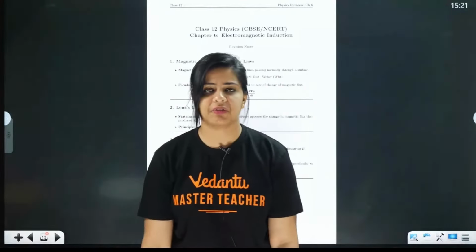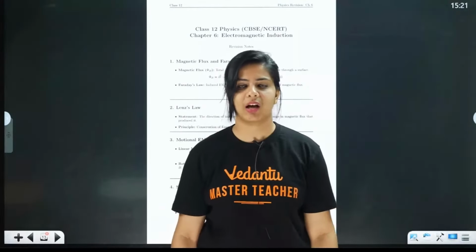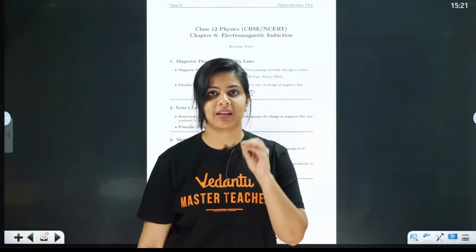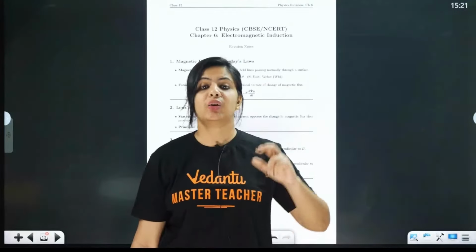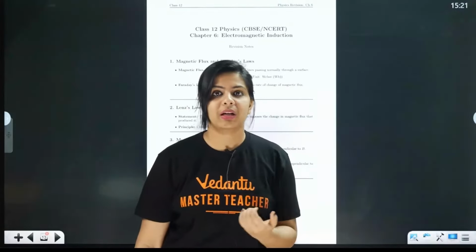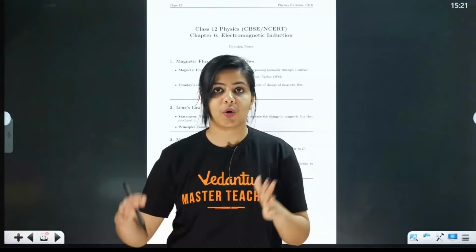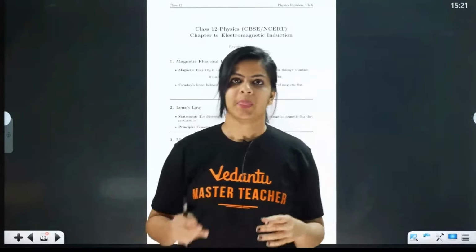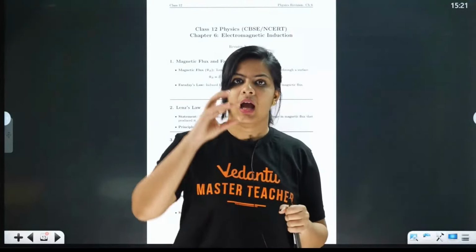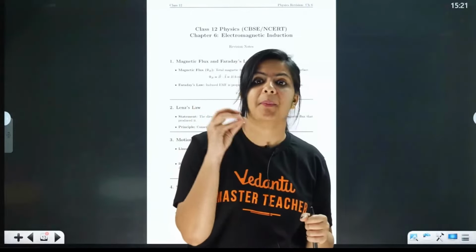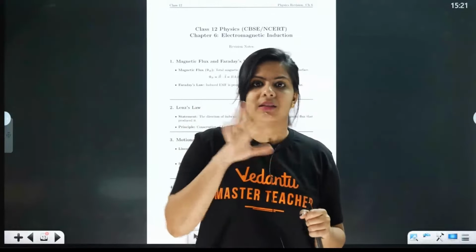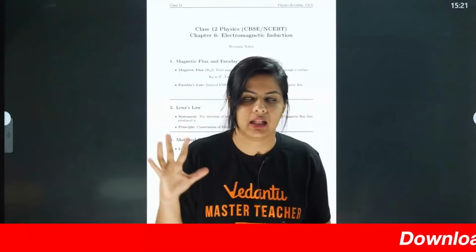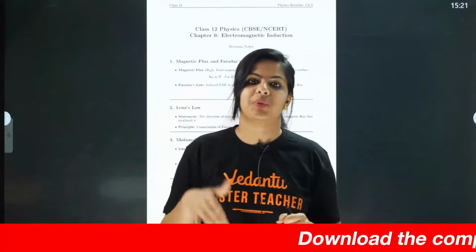Now we are going for Faraday's law. Faraday's law is very simple. If there is a flux change, an induced EMF will be produced. So the induced EMF is equal to minus d phi by dt. In Faraday's law, he gave the magnitude of the induced EMF but gave no idea about the direction, and we got the direction from Lenz's law.